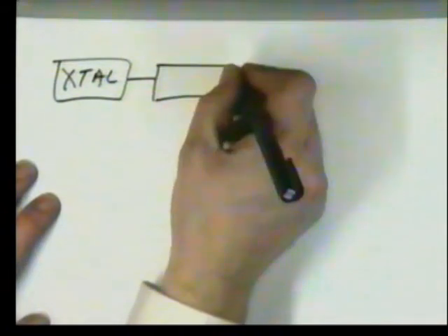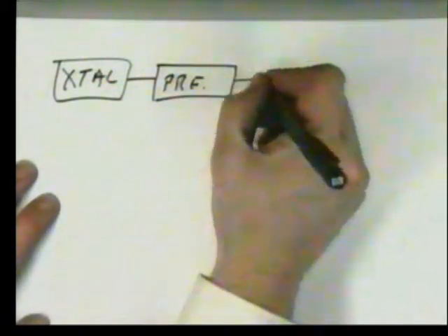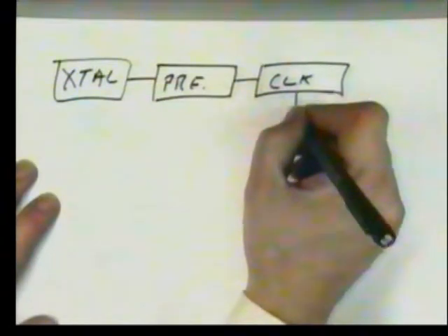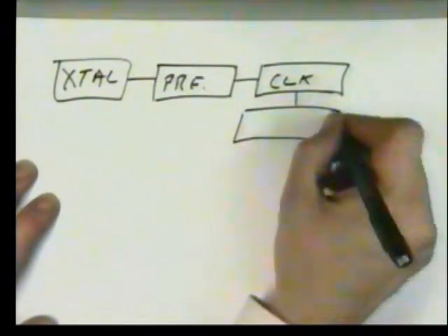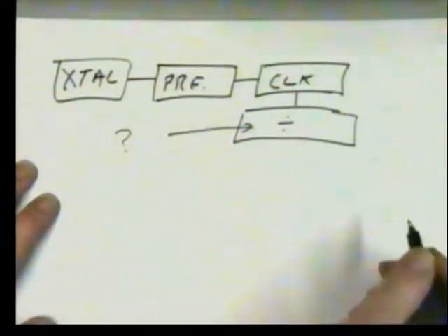What about frequency measurement? That's a different story. Now remember, our device has a crystal. That crystal is divided down by a prescaler to give us the basic clock within the computer system. That would then go through some form of programmable divider, which you have to put your value into.